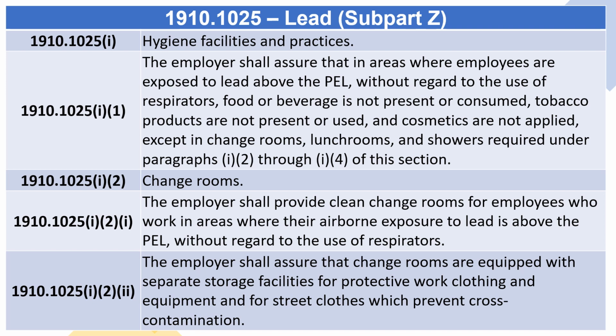1910.1025 I2 Change rooms. 1910.1025 I2(i) The employer shall provide clean change rooms for employees who work in areas where their airborne exposure to lead is above the PL, without regard to the use of respirators. 1910.1025 I2(ii) The employer shall assure that change rooms are equipped with separate storage facilities for protective work clothing and equipment and for street clothes which prevent cross-contamination.